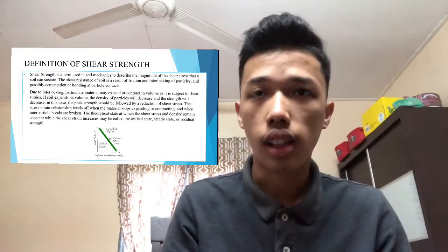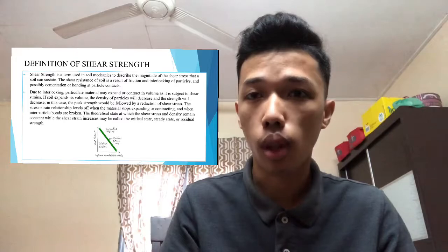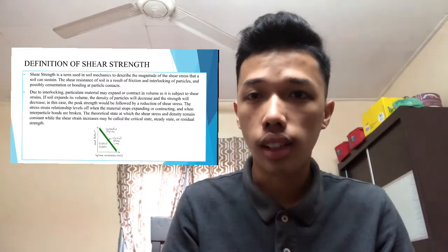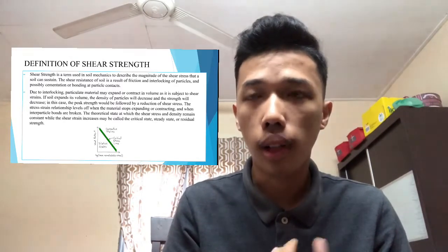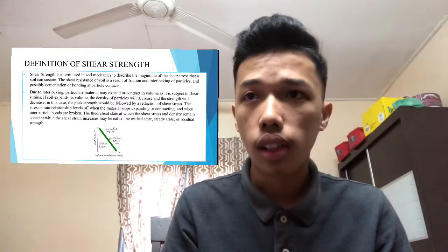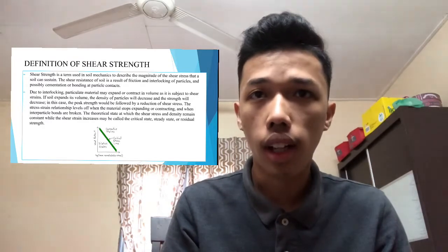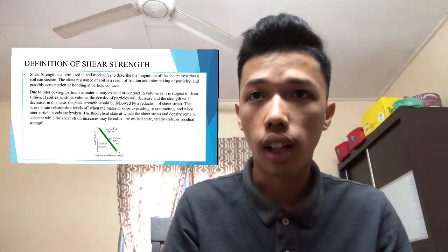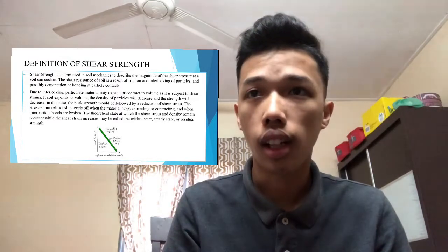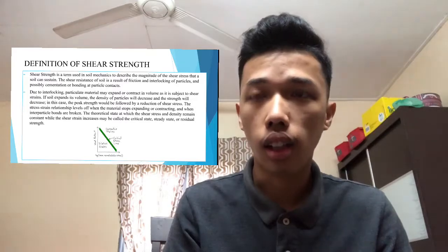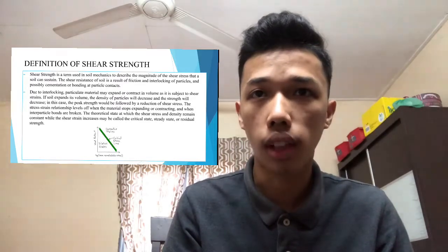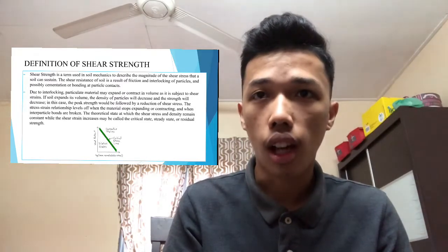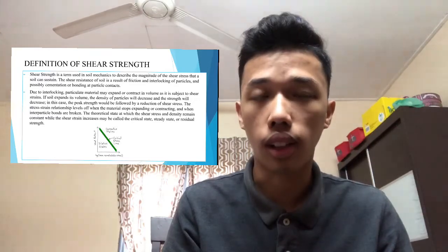Shear strength is a term used in soil mechanics to describe the magnitude of the shear stress that a soil can sustain. The shear resistance of soil is a result of friction and interlocking of particles, and possibly cementation and bonding at particle contacts.